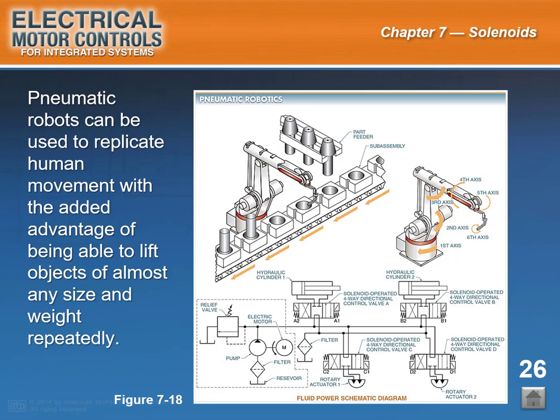Industrial robots use fluid power, where fluids are defined as either hydraulic liquids, usually oils, or pneumatic gases, often ambient room air. These fluids are used in cylinders containing rods or rams for linear motion, or rotary actuators for circular or arc motion, and grippers to provide the required power in movement. The cylinders, rotary actuators, and grippers are controlled by electrical solenoid-operated valves.